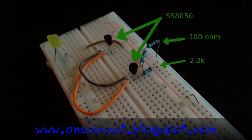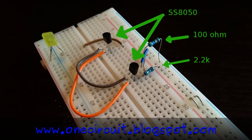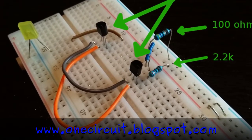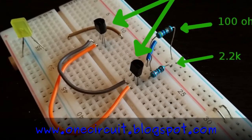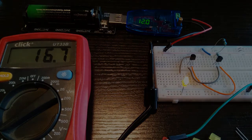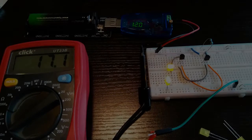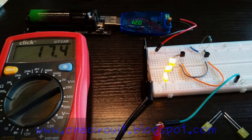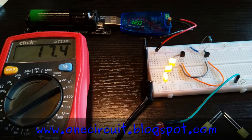Now this is a different setup. This is 2 BJTs, the SS8050, slightly different setup, but effectively operating the same, doing current limiting as I increase the number of LEDs. So with 100 ohms, we've got 16.7 milliamps, 1 LED, and then 17.1 milliamps with 2 LEDs, no current limiting resistors on those LEDs, 17.4 milliamps with 3 LEDs,